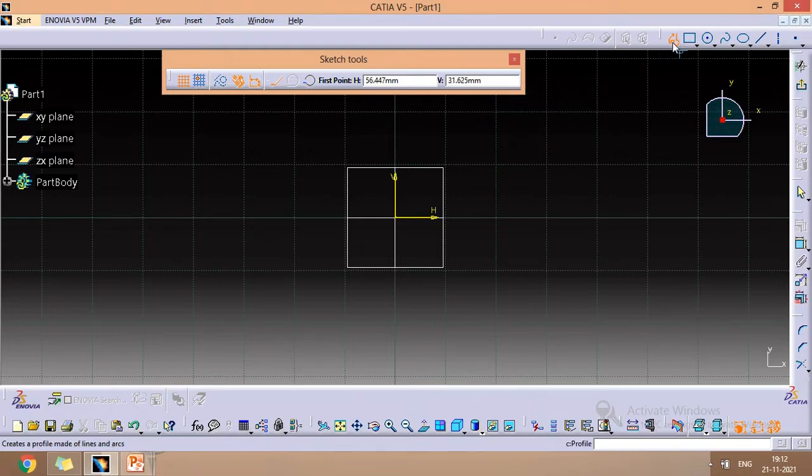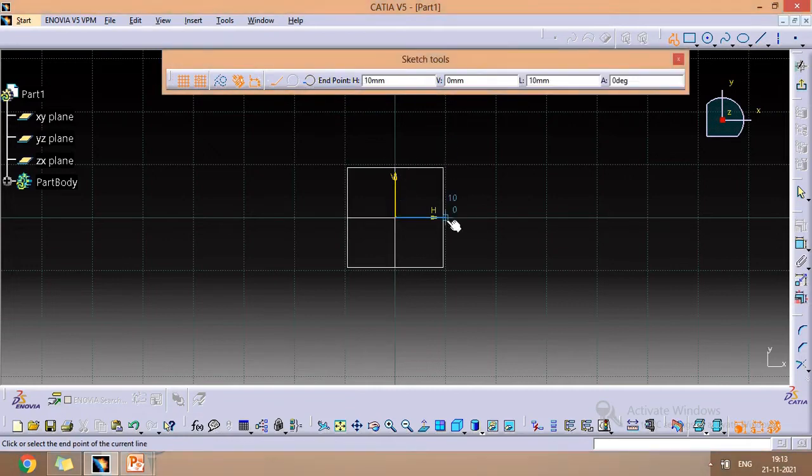For example, we are trying to draw one profile. Start from this point. When snap is on, we get the rounded value as 0, 0. If we are away from that intersection, we still get the rounded value of the intersection point of the grid. Just draw one line.